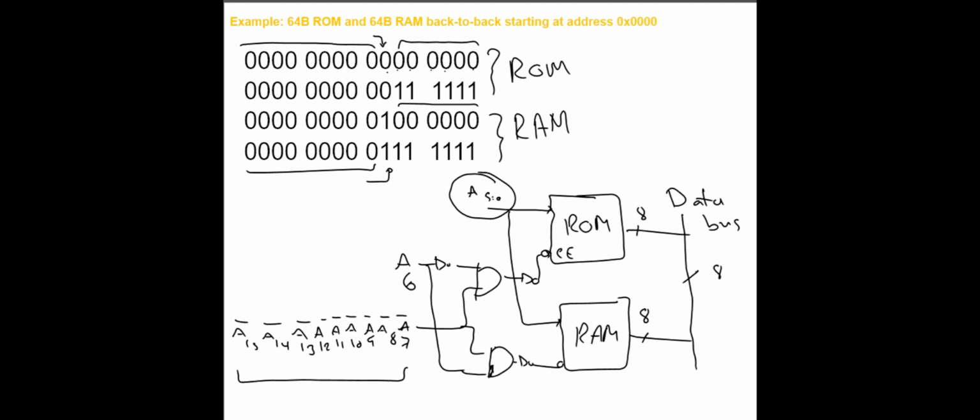And that's it. This is how we do memory address range, and that's how we can refer to this range to help us figure out what goes into the address decoding for the different types of ROM or RAM. Theoretically speaking, you can use the same thing to calculate the ranges for different chips if you need, within the same memory type. Or you can use the method that we've covered in a previous video.